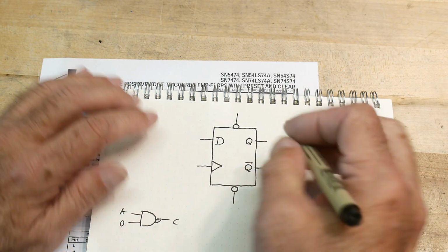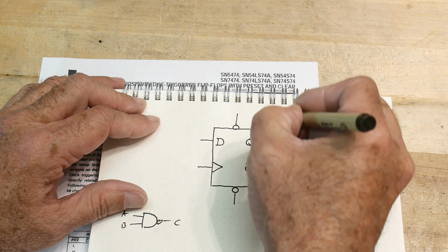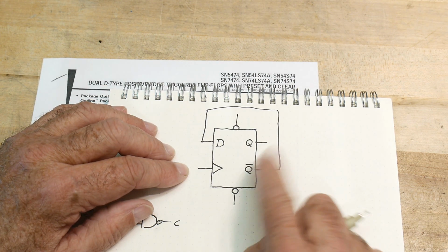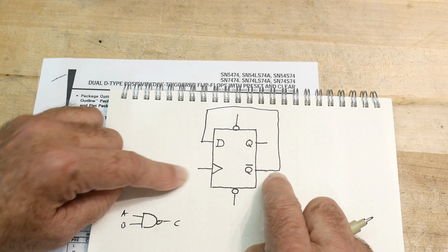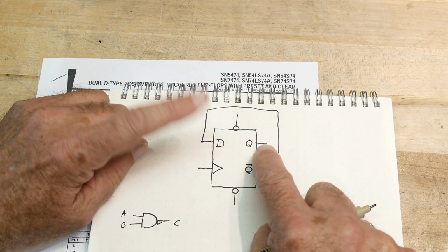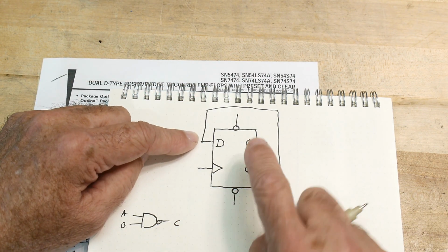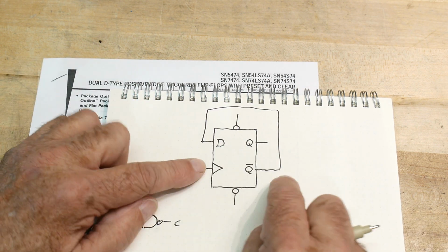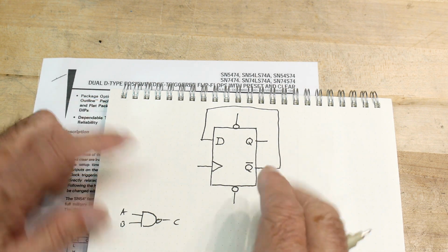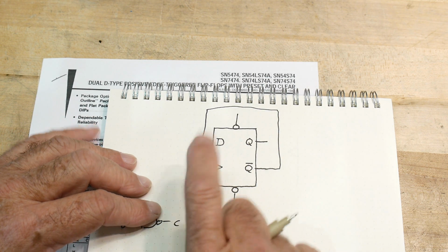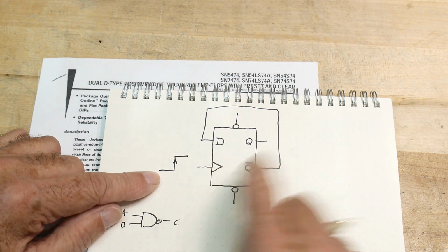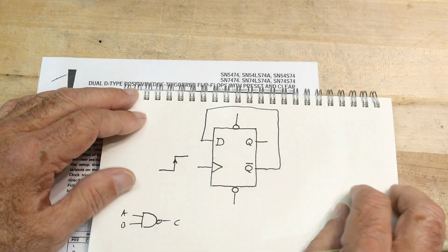And in these circuits, one of the very first things you learn is to do this: connect not Q back to D. Let's say that not Q is 0. Then on the next rising edge, this 0 will make this 0. It'll sample that 0 and make Q 0. If Q is 0, then not Q is 1. The next time you see a rising edge, D is a 1, and if you clock that, then Q becomes a 1. And so it'll count: 0, 1, 0, 1, 0, 1. It'll only do so on rising edges. And that's the way you make a flip-flop counter.